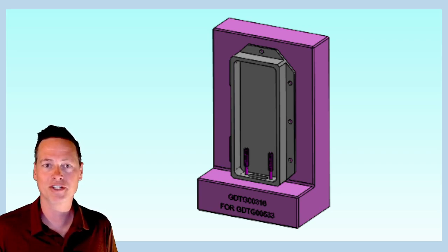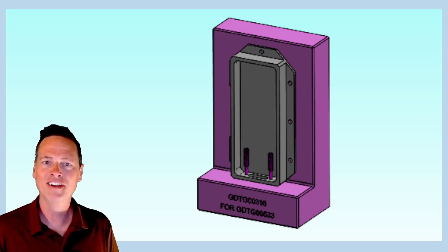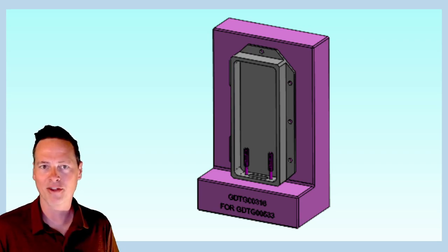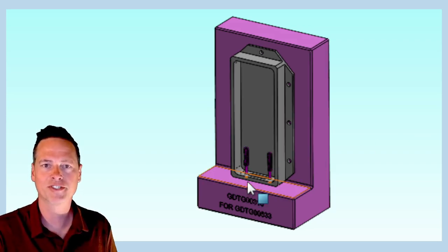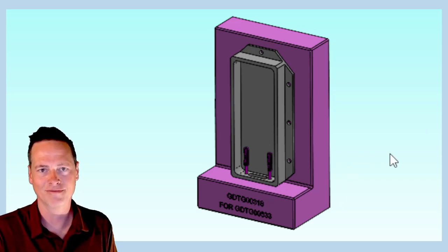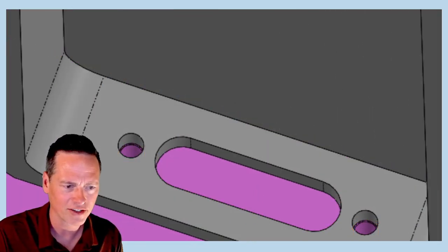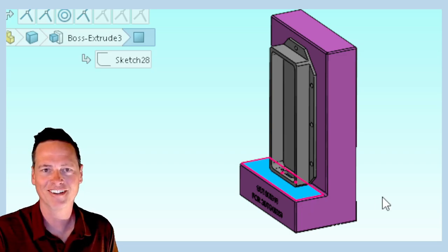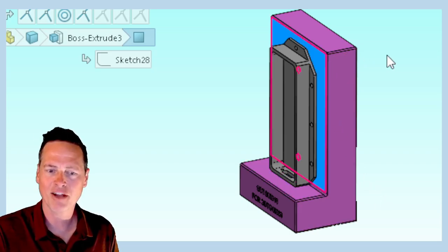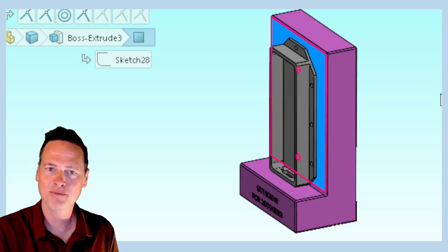What I like to do in a situation like this is to imagine an inspection fixture. And I make them purple so that you can recognize them and you can think about them as being highly geometrically accurate. Perfect for our purposes. So this fixture would have datum simulators for C, A, and B at MMB. And then there are 2 holes in the fixture down here for our hole locators. So we would set our housing part down on this datum C simulator and then slide it toward the datum A simulator until it makes 2 points of contact, right? Does this seem plausible so far?